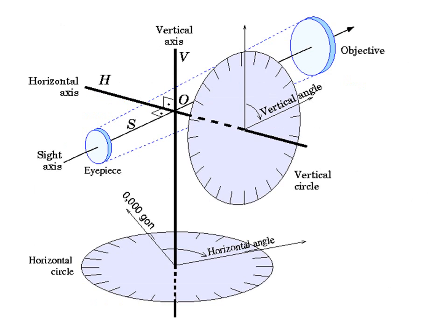So again in this slide I have tried to show the different fundamental axes. One is the vertical axis, another is the horizontal axis, third is the axis of the telescope, and the graduations on vernier C and vernier D, showing how the vertical angle is recorded. At the same time, the horizontal circle graduations are generally in a clockwise direction. We are going to record the angle with respect to a particular direction by setting vernier A to 0 degrees and B to 180 degrees.